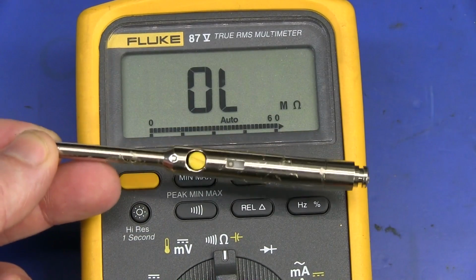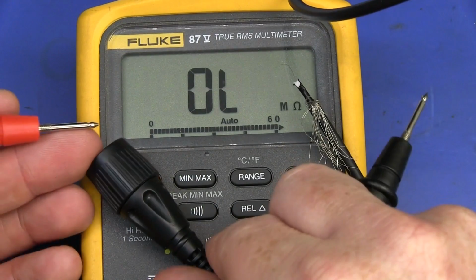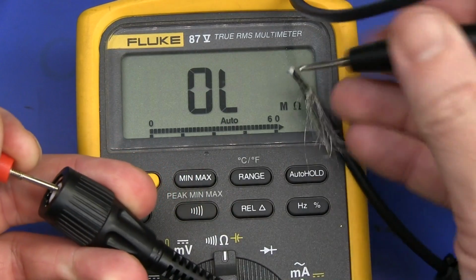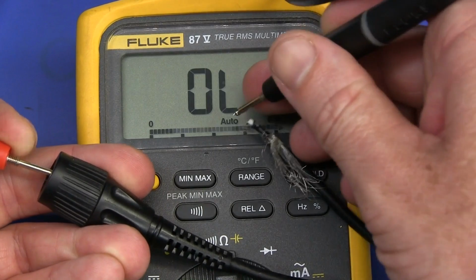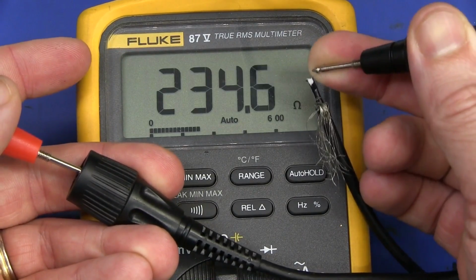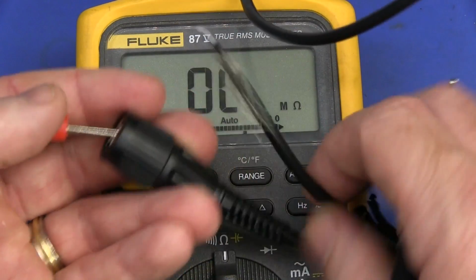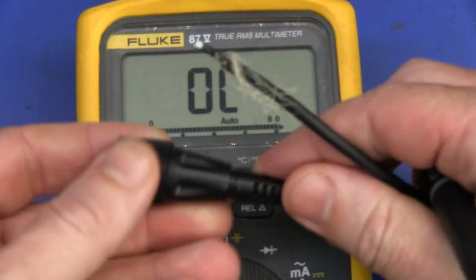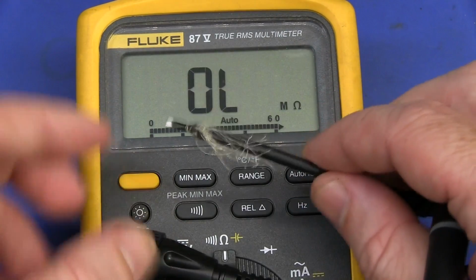It must be in the coax or the end of the coax. And here's the part of that chopped off Velleman probe, and let's measure it. There we go, and the fine wire, I'll get a very good close-up of this in a minute, but basically I'll have to hold my finger on there, I'm not touching the other one. There you go, 230 odd ohms. This oscilloscope coax, and trust me folks, there's no series resistor or other circuitry inside there. I could chop it open to prove it, but I couldn't be bothered.